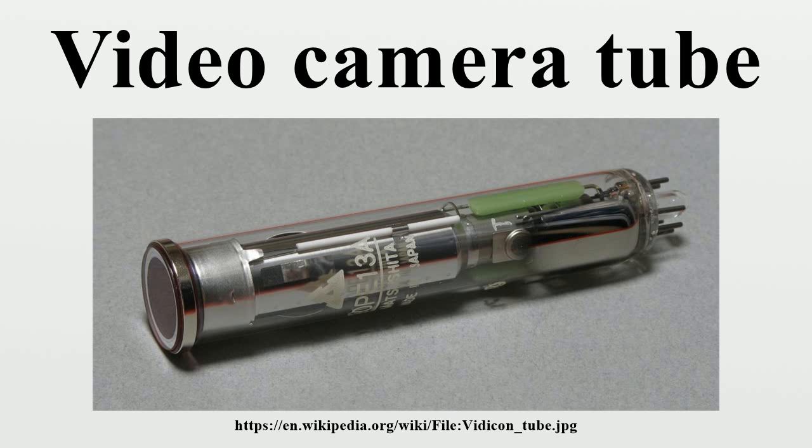The EMI team, under the supervision of Isaac Shoenberg, analyzed how the Emitron produces an electronic signal and concluded that its real efficiency was only about 5% of the theoretical maximum. This is because secondary electrons released from the mosaic of the charge storage plate when the scanning beam sweeps across it may be attracted back to the positively charged mosaic, thus neutralizing many of the stored charges.